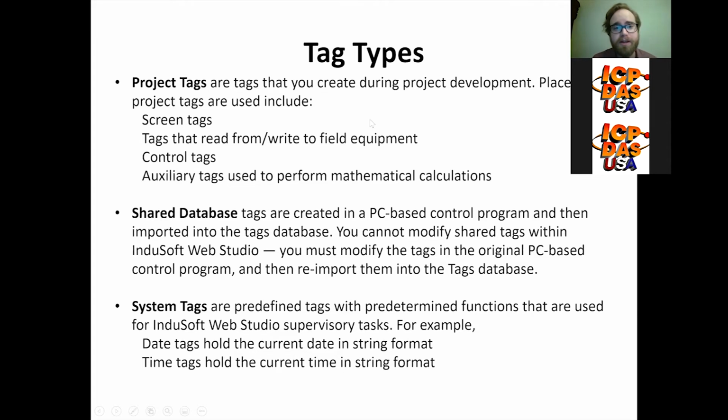So shared database tags, these are different from project tags, are created in a PC-based control program and then imported into the tags database. So you cannot modify shared tags within Indusoft Web Studio. You have to modify them in the original PC-based control program and then re-import them into the tags database. So the shared database tags are going to be your global tags that you don't want to change inside of an individual project, because one system or one plant, one operation may have many different Indusoft projects inside of it. Probably will have many different Indusoft projects inside of it. So there are some tags that you just don't want changing within each of those projects.